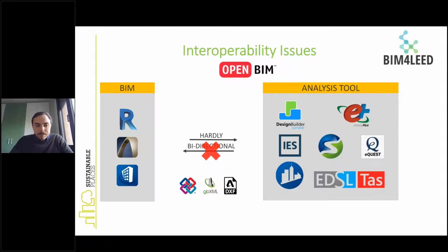So we can develop our model and put our BIM model in the analysis tool, but if we do some modification or revision in the analysis tool, we have to go back to the BIM tool and re-export the IFC model.